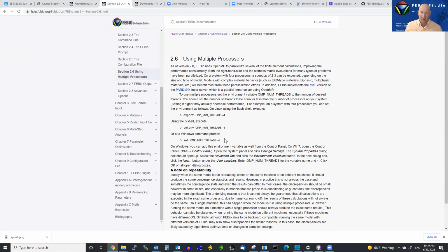There are a few classes of problems that seem to be really amenable to this. The types of things we encounter in biomechanics that work well with iterative linear solvers are, for example, modeling the explicit structure of a chunk of cancellous bone. You have micro CT image data, and you convert it into geometry and maybe map the Hounsfield number onto the model, so you have a position-dependent modulus.